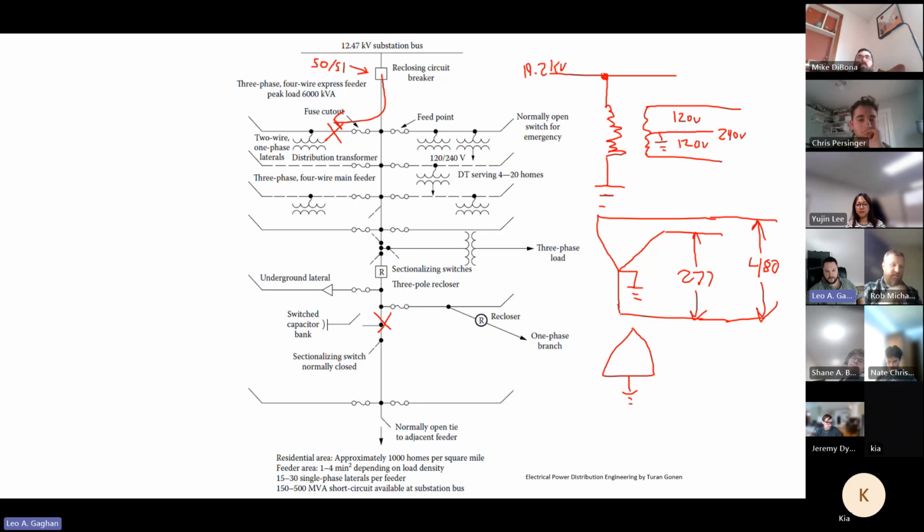Then there are different combinations. This one's a little weird: this is that center tap there, and you could technically get a voltage from this value or from that value. That gives you one more option. Like I said, there's a handful of different transformer configurations. But at your house, this is definitely the most common one. In an industrial facility, you might see something different.